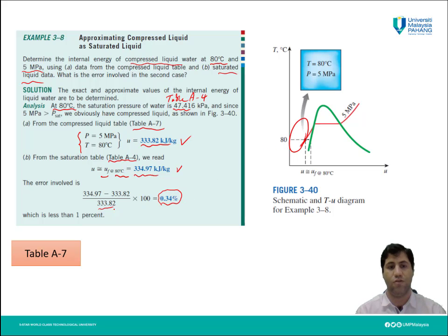So we can also use this method instead of referring to table A7. We can use this method to find the properties for the fluid, for the liquid which we have here in this region, in the compressed liquid region.